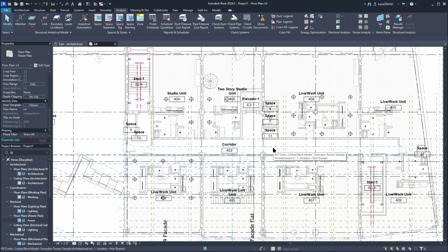and you can see it's pulled in the names and numbers for most of these spaces. It's not perfect. Some of them don't get populated, which means you'll need to either do some manual coordination or just run cleanup on some of these spaces. A few of them seem to be voids in the architecture or chases for HVAC or wiring. But doing that cleanup will probably take less time than it would take to create and configure these spaces manually.